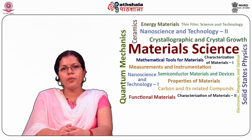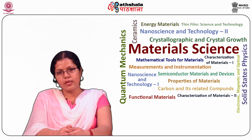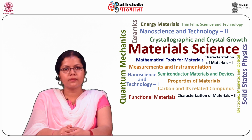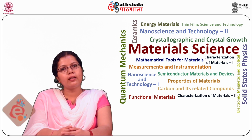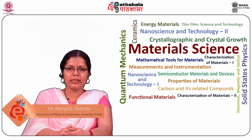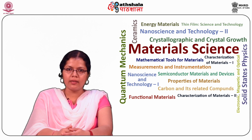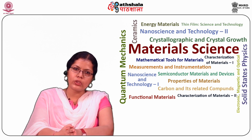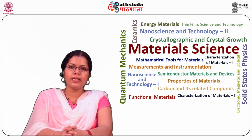We also studied about Q measurement by measuring impedance. Two different schemes of Q measurement have been proposed depending upon the nature of the impedance measurement. These are the series connection scheme for low impedance and the parallel connection scheme for high impedance. Both the schemes have been studied in detail and with derivations. Then we studied about the Meggers, which are instruments used for the measurement of high resistance and insulation resistance. We studied about the operation of Meggers and the continuity tester.